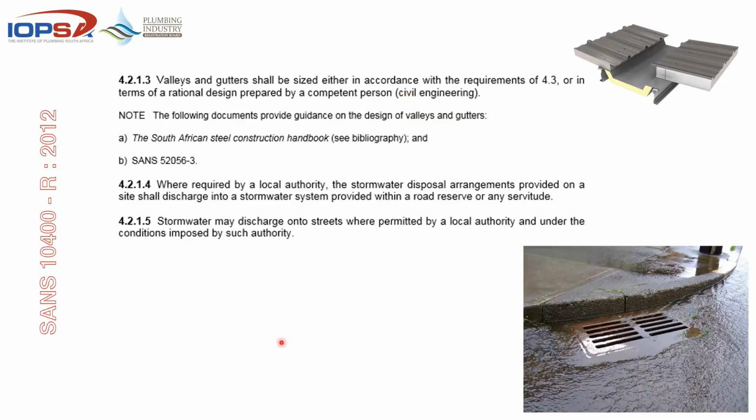Where required by a local authority, stormwater disposal arrangements provided on site shall discharge into a stormwater system provided within a road reserve or any servitude. The stormwater may discharge onto streets where permitted by a local authority under the conditions imposed by that local authority.